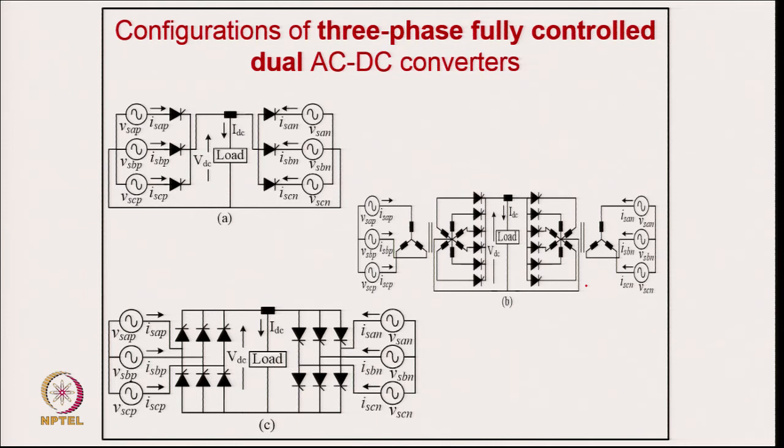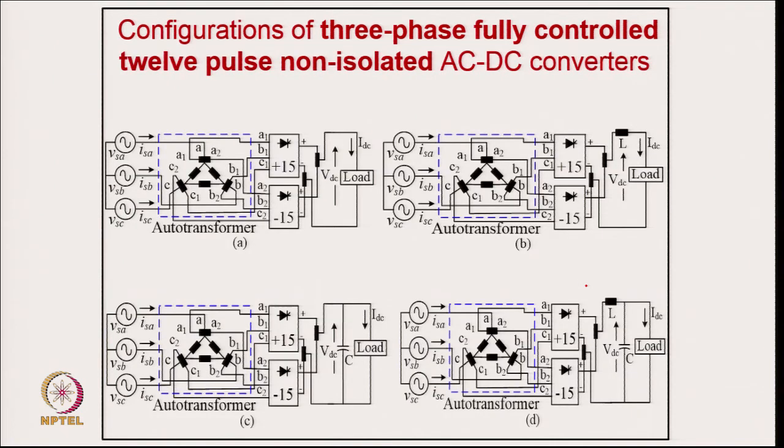They also draw harmonics and reactive power from the supply, but of course the load can give four quadrant operation, like a DC motor drive, or you may be using it for other applications, like a 12 pulse converter. Harmonics get reduced because harmonics below the 11th are not there, but 11th, 13th and higher orders are still there, and apart from that it draws reactive power. So control of output voltage comes at the cost of reactive power drawn from the supply system.